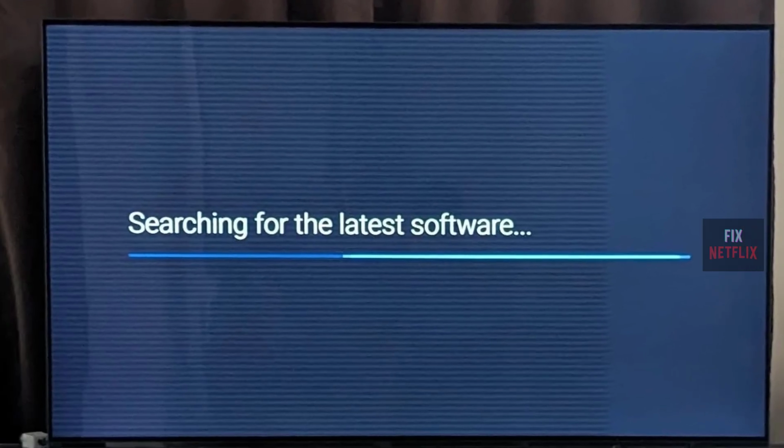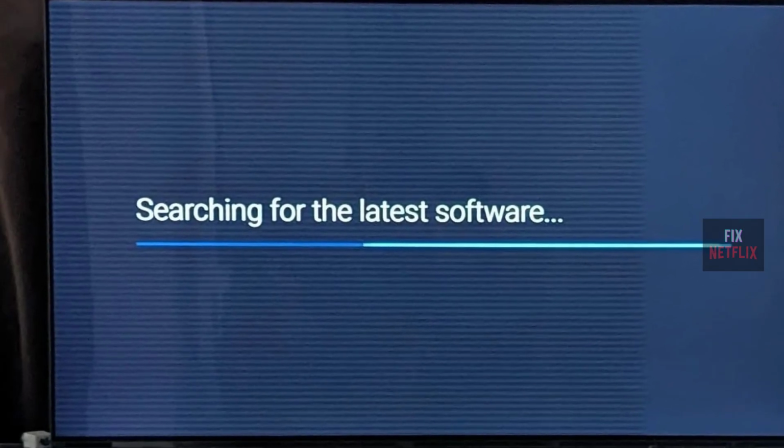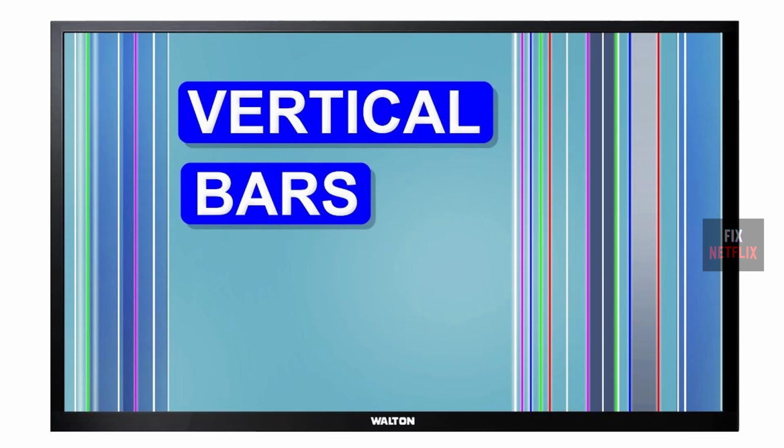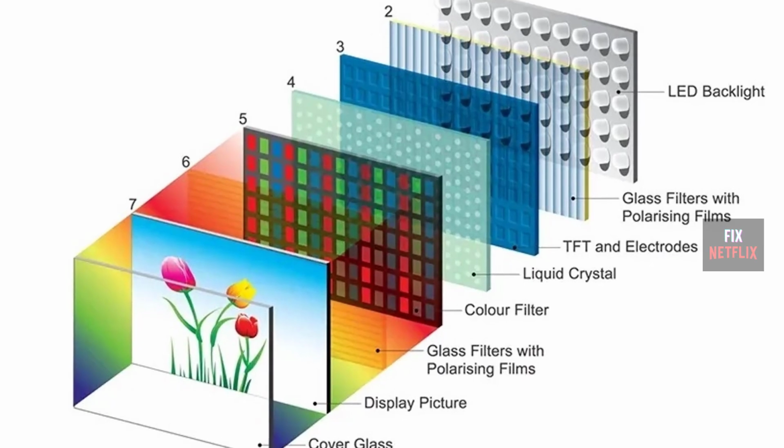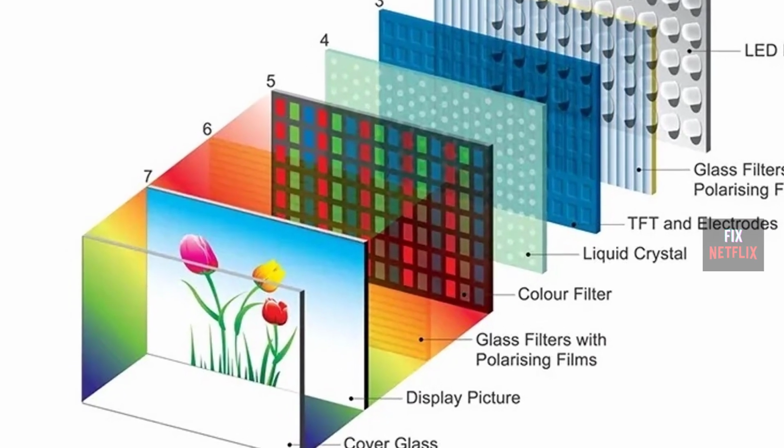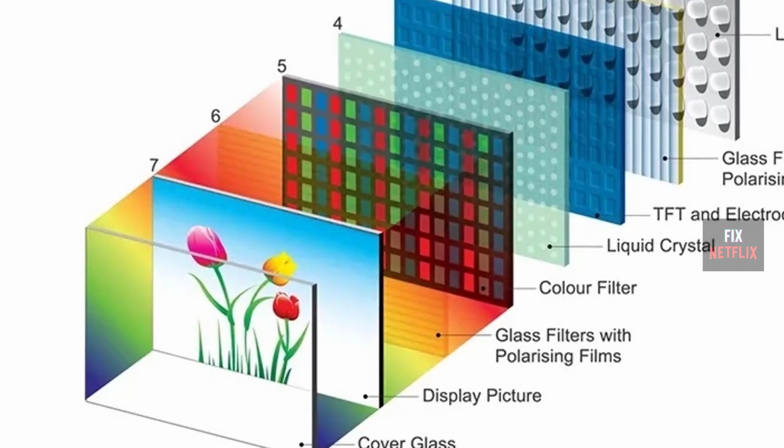A common sign of panel failure is single horizontal or vertical lines in the image on the screen. Many panel failures can be traced to physical abuse. Further, the construction of the panels with chips embedded in flex plastic or attached to glass makes them vulnerable to unrepairable failures in those devices that surround the panel periphery.